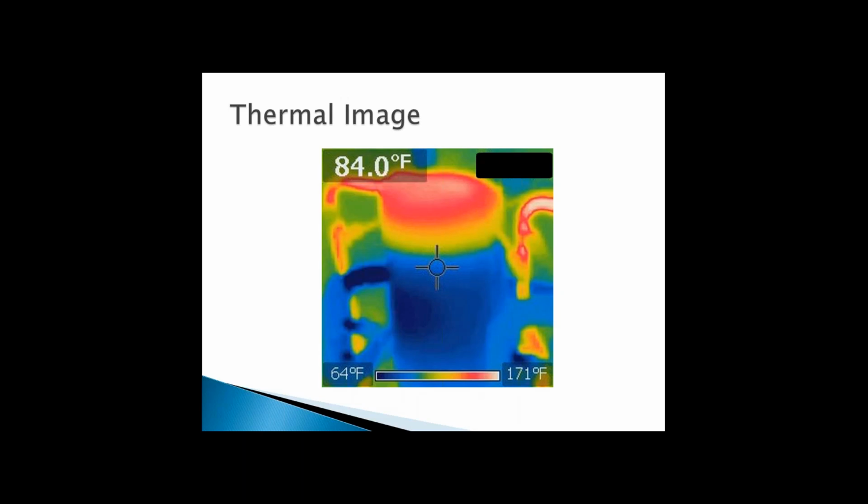Right here is a thermal image. This is basically the heat signature produced by an infrared camera of a scroll compressor operating properly. As you may know, with a scroll compressor, relatively low temperature, low pressure refrigerant vapor enters the bottom, and higher temperature, higher pressure vapor is discharged out the top. This thermal imaging camera picture is showing the heat being emitted from the specific object, and that camera assigns a color and temperature value to it.